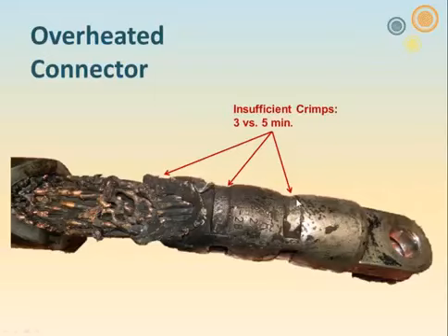Now, we know it was torqued together properly. Remember I mentioned that there should be a mark? You can just see the surface of the lug here. That outline is exactly 1 1/4 inches in diameter, and that's where the bushing contact or the insulating plug contact moved around the surface and smoothed it off. We saw this impression on both sides, so we know the torque was proper over here.